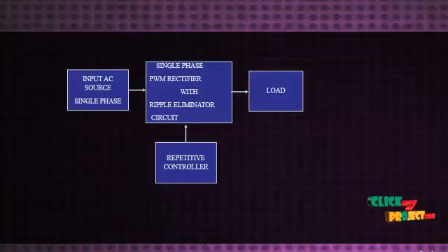All electrolytic capacitors are polarized capacitors whose anode is made of a particular metal on which an insulating oxide layer forms by anodization. Acting as the dielectric of the electrolytic capacitor, a non-solid or solid electrolyte which covers the surface of the oxide layer in principle serves as the second electrode, the cathode, of the capacitor.